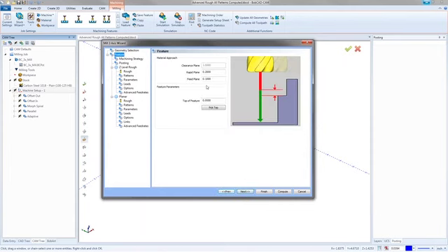So next, right here's our feature page. Clearance plane is at 1 inch like the default. 200 thou, 100 thou for the rapid and feed respectively. And then my top of feature is pretty well always going to be a 0 unless I'm showing you guys some stuff on a router, in which case a lot of times those routers go off the bottom of the stock instead of the top. So you'd have a negative, whatever the thickness of your material is there.